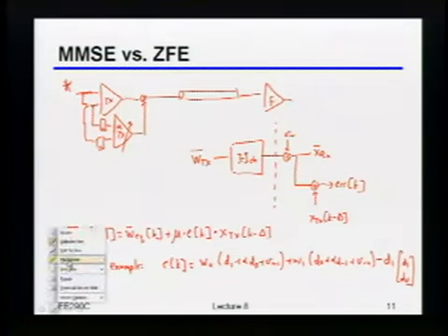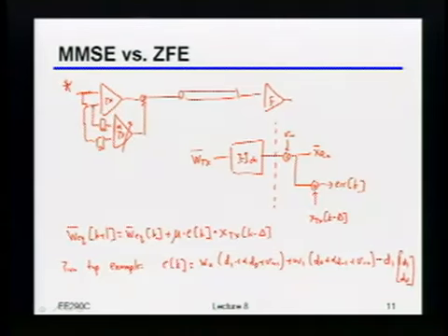So when I multiply that by D1, is there any hope for me to see what the noise variance is? No, right? Because when I multiply D1 by the noise, both here and there, on average it just gets knocked out, because there's no correlation there. The only terms left are the correlation between D1 and D1, and of course the correlation between D0 and D0. So in other words, you're completely ignoring the noise. The only thing you're going to do is try to drive anything associated with the data to be 0. That's just another way of saying that in this instance you're trying to kill the ISI completely, because there's no noise to stop you from going after completely killing the ISI. Does this make sense to people?